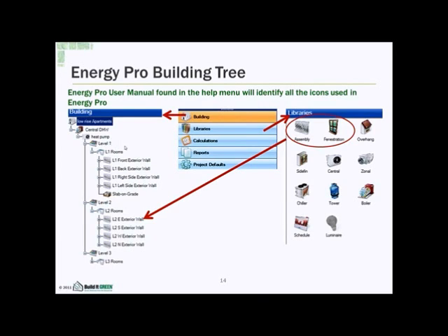You right-click, it'll say Add Room, and you add the room, and this icon will pop up with a kind of default name, and you'll go ahead and name your room accordingly. And this room is representative of that floor level. It's a block load. It's not a unit-by-unit analysis.